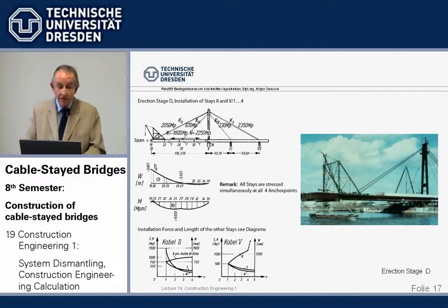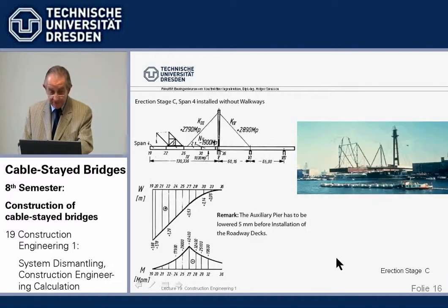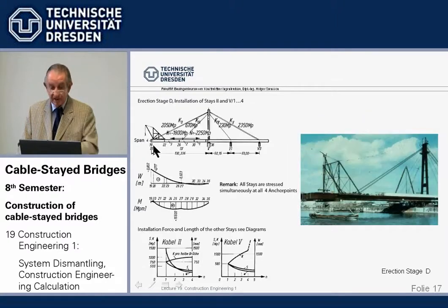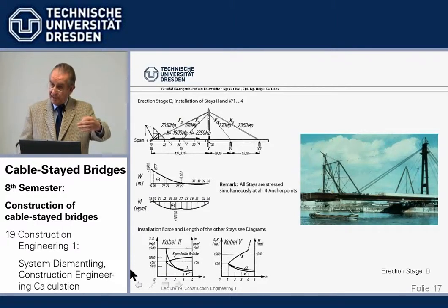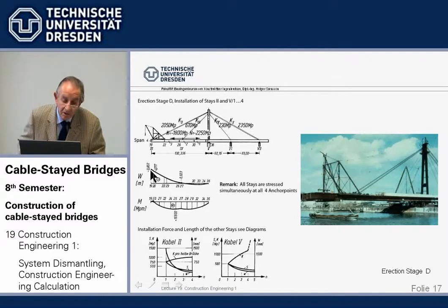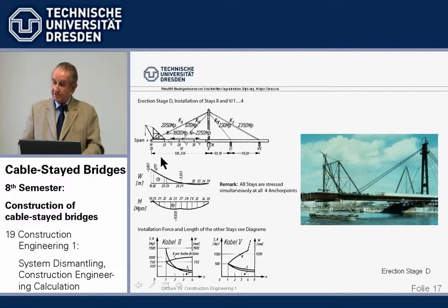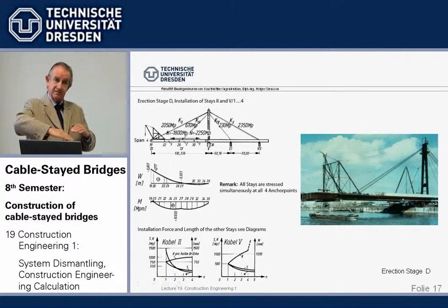Now, we have now installed, the difference between the two is, here we have cantilevered the beam, but the cable isn't in. Here we have just installed, we haven't done anything to the beam, but we've just installed the stay cable. So, what happens with the tip? From 1.88 meters down, before a cable installation, we are now 0.8 meters up. So we have a movement of 2.6 meters during cable installation, up 1.8, up 0.6.